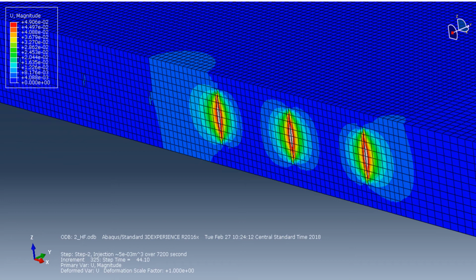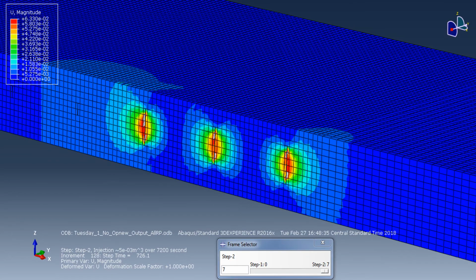By increasing the injection rate 500 times between 2 simulation trials, we saw that with a higher injection rate, fracture growth is concentrated mostly in height, then propagates through and increases width. The lower injection rate seen here also shows more defined fracture initiation around the initial crack, but does not exhibit as much height growth.